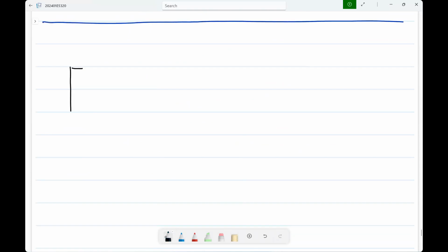Let's say you make 1,000 identical units like this on a chip, or any number. Everything is the same. The direction is the same. The width and length exactly are the same. You have identical environments, etc. They will still have different resistance values.